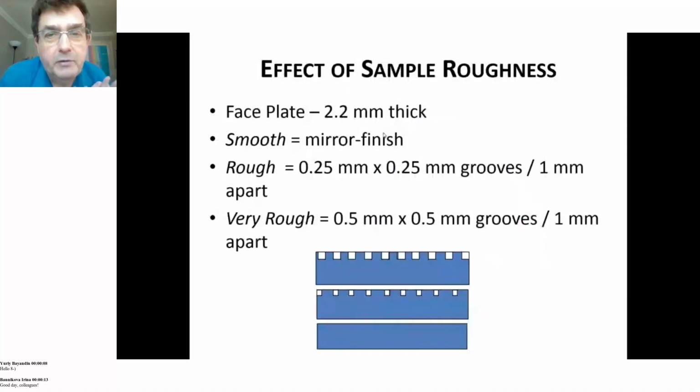Then let's have a look at sample roughness. Now, sample roughness in Hopkinson bar experiments is not such a big effect, because in Hopkinson bar experiments, we're looking at bulk failure, bulk flow of the sample. There are waves in the system, but it's not particularly a wave-dominated response. Here in this system, in shock waves, we've got a wave-dominated response. So therefore, surface roughness and things that affect the initial transmission of waves is important.